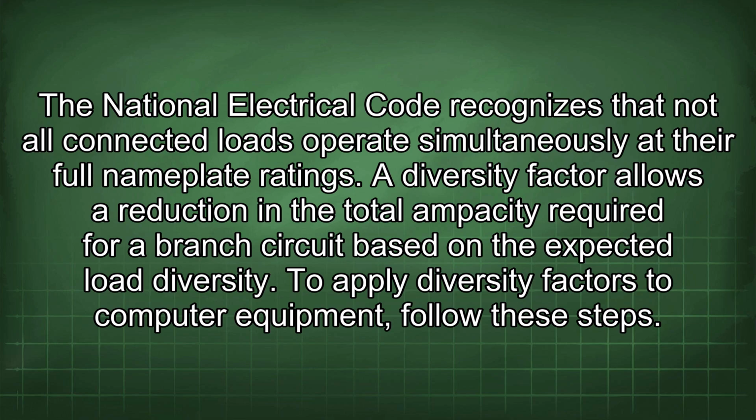The National Electrical Code recognizes that not all connected loads operate simultaneously at their full nameplate ratings. A diversity factor allows a reduction in the total ampacity required for a branch circuit based on the expected load diversity. To apply diversity factors to computer equipment, follow these steps.